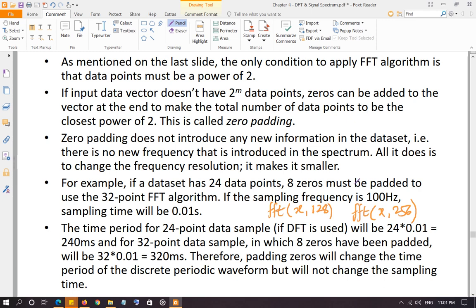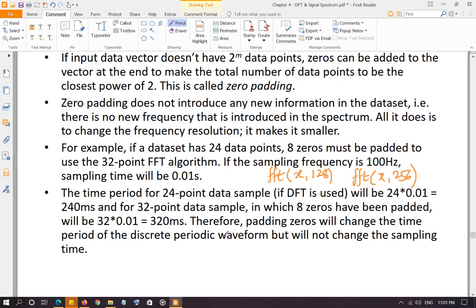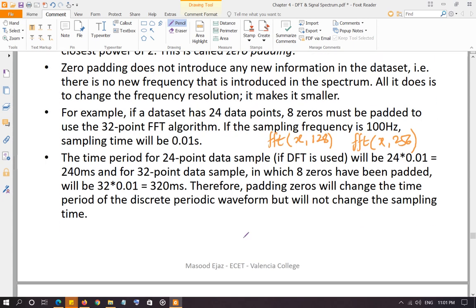It's going to calculate the DFT using the FFT formula with 1024 points. That is going to pad a bunch of zeros towards the end after the original data that you have. Okay, so remember that. Don't physically start putting them in. If you're using the FFT function, just put down the number of points that you want after the input vector.